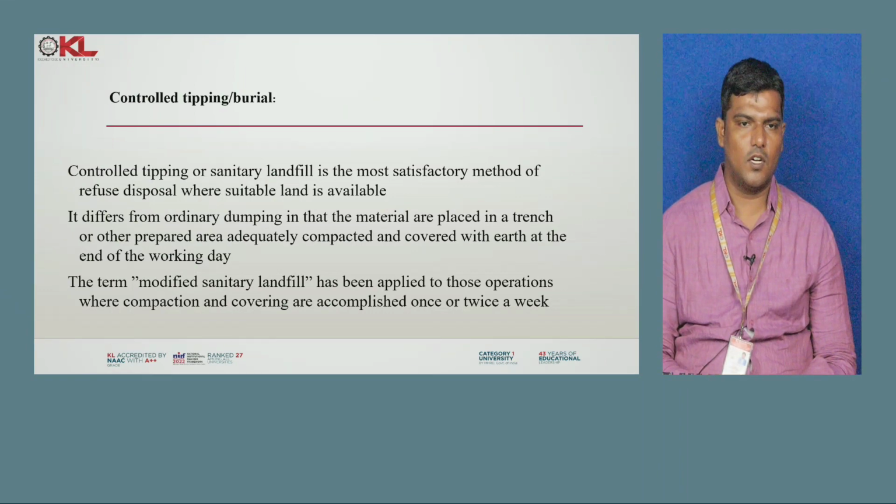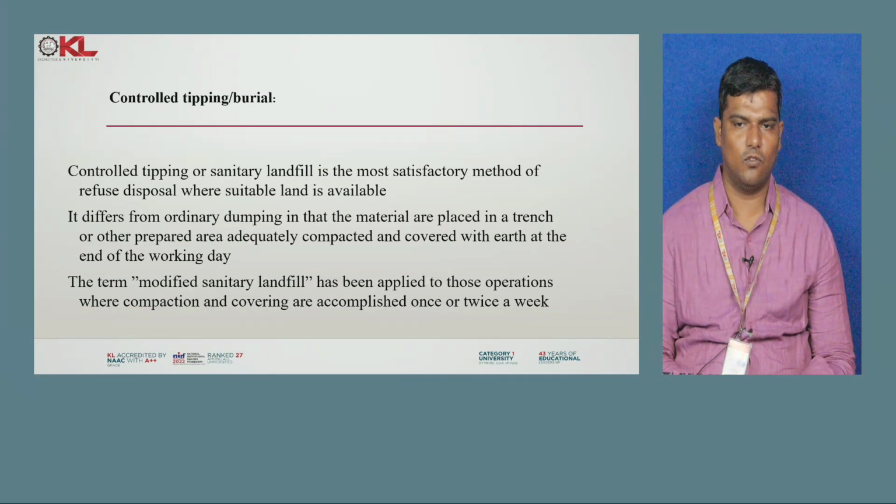Generally controlled dumping or sanitary landfill is the most satisfactory method of refuse disposal where suitable land is available. It differs from ordinary dumping in that material is placed in a trench or other prepared area, adequately compacted and covered with earth at the end of the working day. The term modified sanitary landfill has been applied to those operations where compaction and covering are accomplished once or twice in a week.